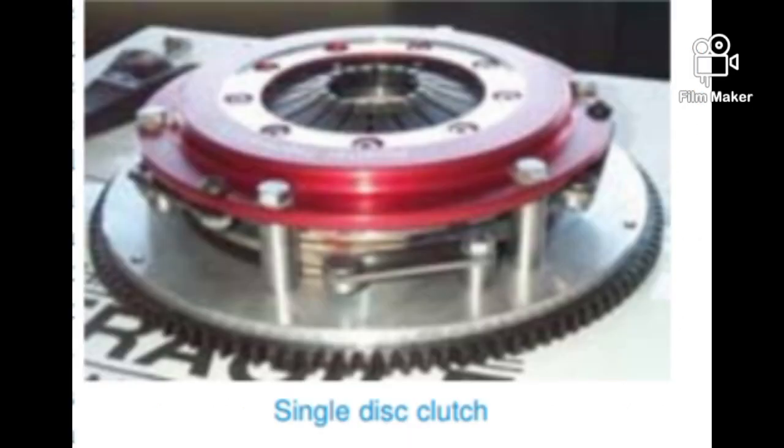The figure shows the single plate clutch. A single disc or plate clutch consists of a clutch plate whose both sides are faced with a friction material. It is mounted on the hub, which is free to move axially along the splines of the driven shaft. The pressure plate is mounted inside the clutch body, which is bolted to the flywheel. Both the pressure plate and the flywheel rotate with the engine crankshaft, or the driving shaft.